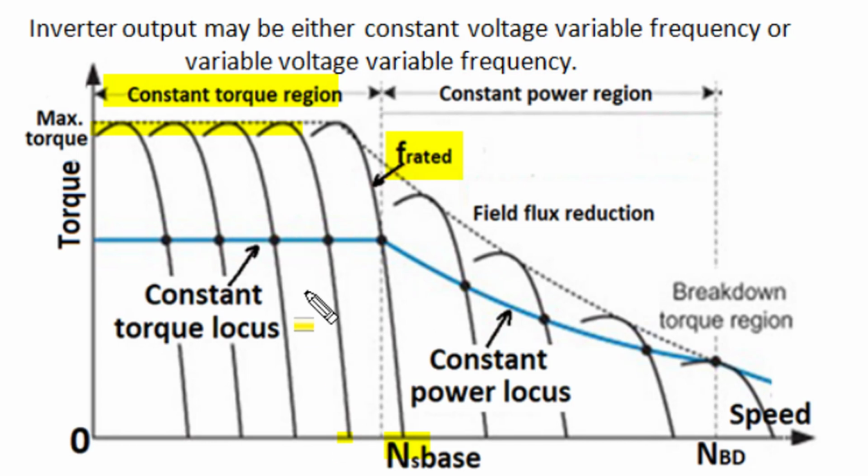For the same amount of slip to maintain constant torque, the motor operating speed will reduce as we reduce frequency and voltage in the same proportion, and reduced frequency maintains constant torque conditions of load at different reduced speed operations. So this reduced frequency operation with constant V by F ratio, voltage to frequency ratio, is also known as the constant torque region of speed control.